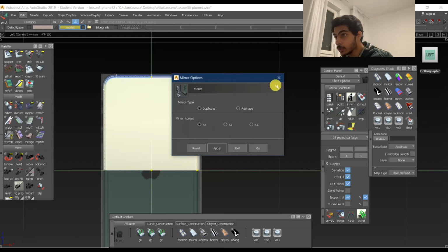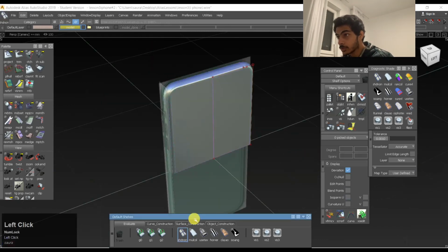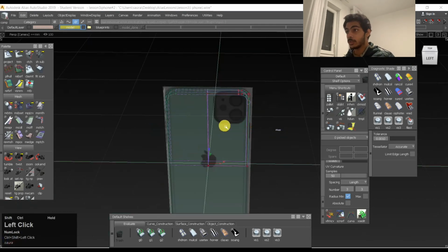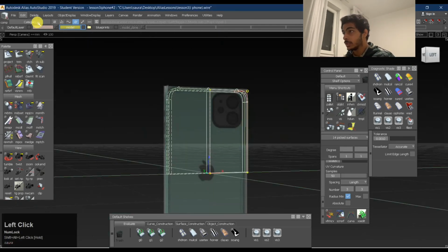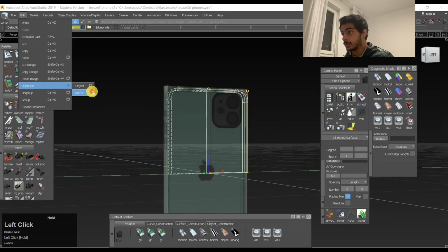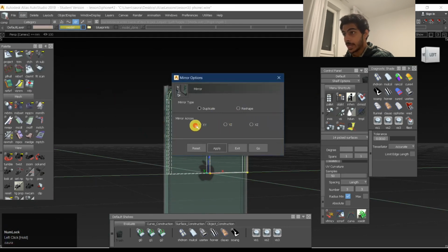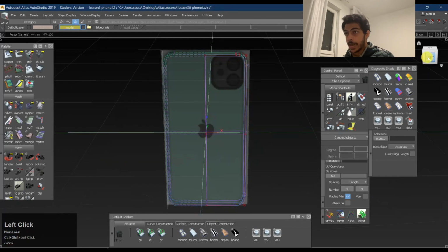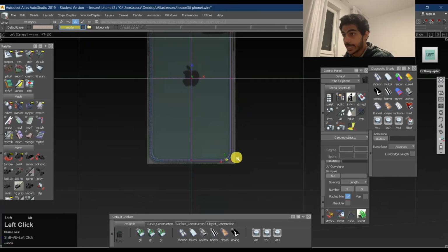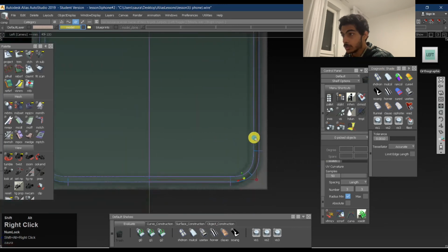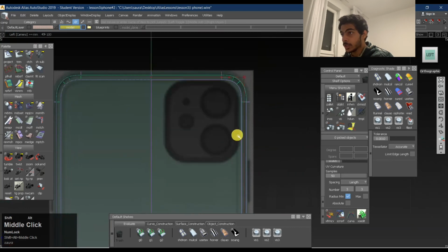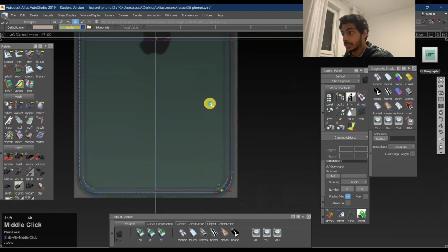If I move it over here, you'll see we are going to reflect it along the X and Y axis, which is going to be reflected down. So we'll just select all these surfaces, edit, duplicate, mirror, and X and Y axis duplicate. Go. You see how it duplicated? And if I look, it exactly matches how we wanted it to. Yep. So that's how it is.